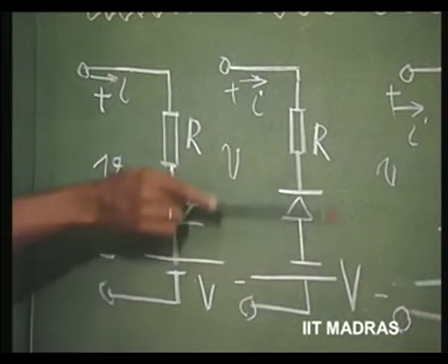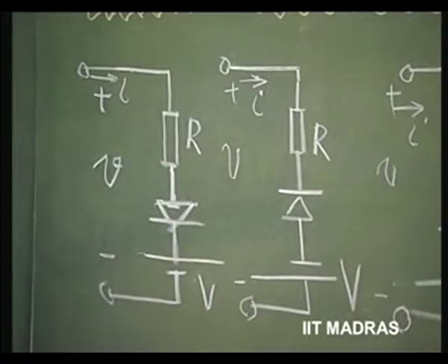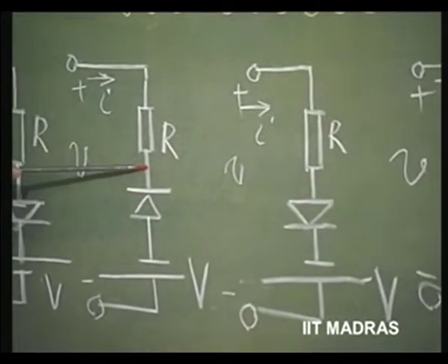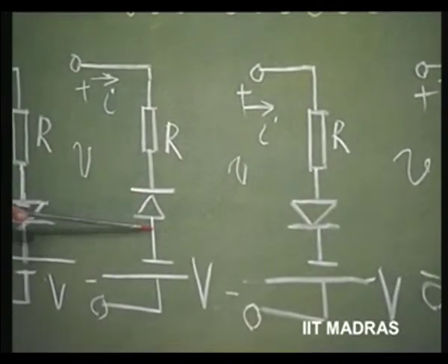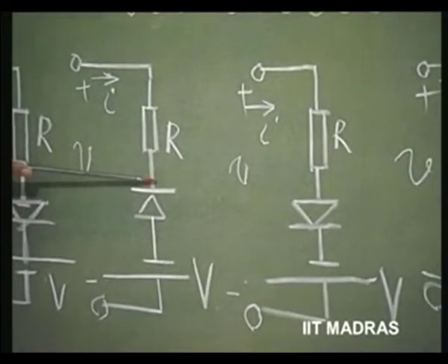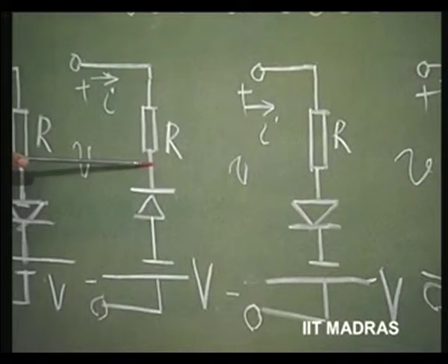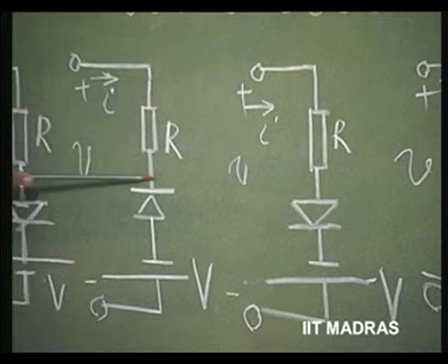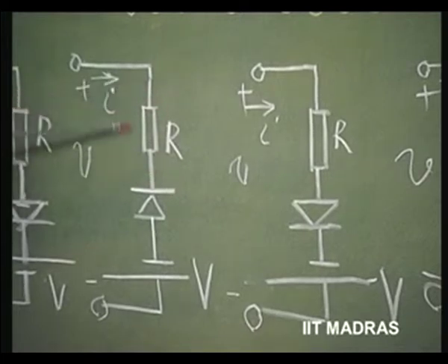This is another one that we had used in example 4, where this resistor came into picture when this voltage here was more negative than this voltage. Let us say this is minus 1 volt. When this is minus 1, minus 2 or minus 3, this diode conducts, and for all those voltages which are more negative than minus 1 volt, this resistor will come into existence. This diode is a short circuit.